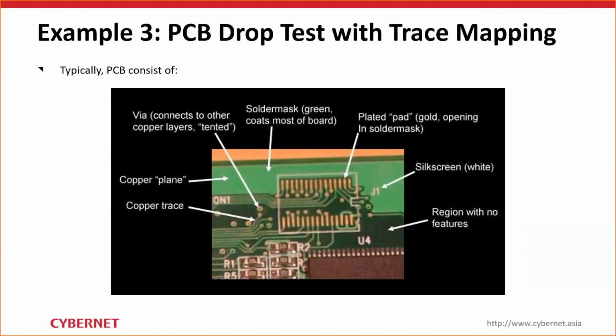For a multi-layer board, conductors on different layers are connected with something known as vias, which is a copper-plated hole that functions as an electrical tunnel through the insulating substrate. So the most commonly used material for the substrate is FR4, with other materials also being used depending on what kind of application you are doing.